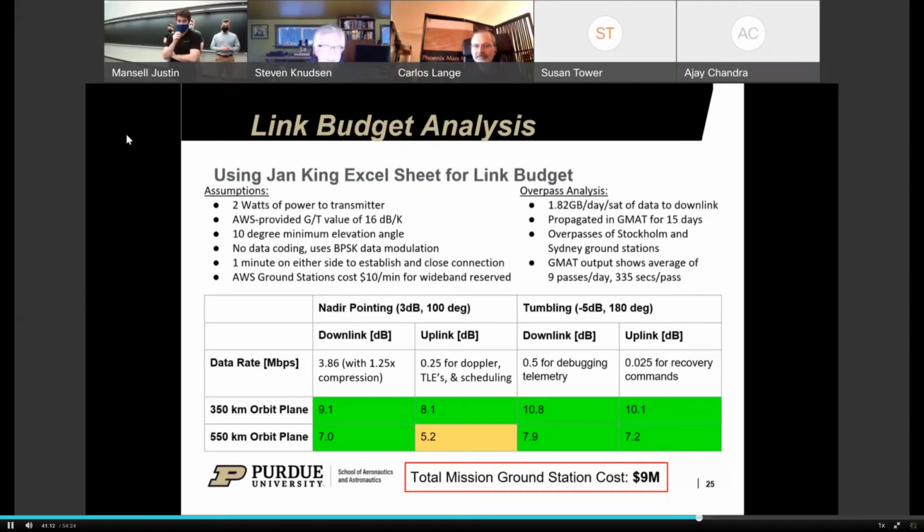Okay, so I'll just end with more of a suggestion. You might want to look sometime at using either higher modulation like QPSK or something like that with forward error correction. Especially since you've got a lot of data coming down, it's very inexpensive to use something like low density parity check as a forward error correction method.